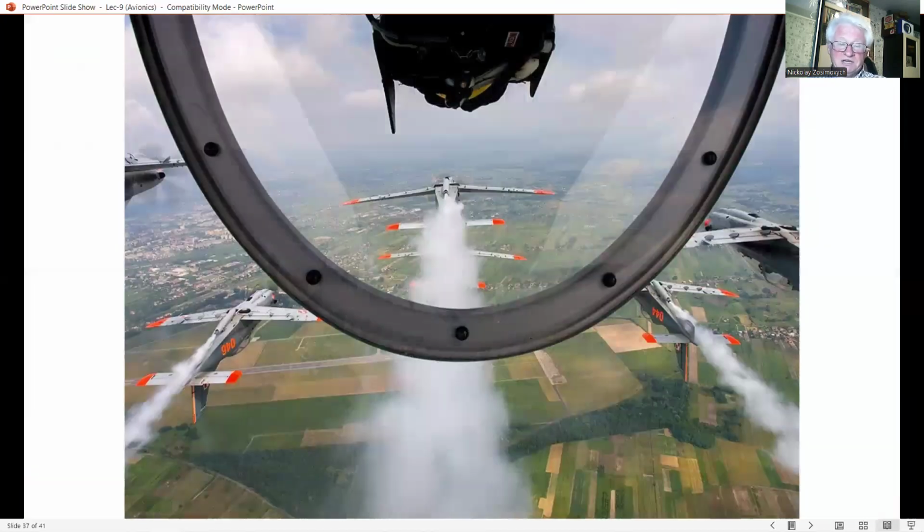An ideal vertical reference system using gyros with negligible drift or bias, once initially aligned with the local vertical, would continue to measure the aircraft attitude with respect to the local vertical using the gyros alone, assuming the Earth's rate and vertical rate corrections were applied without error.